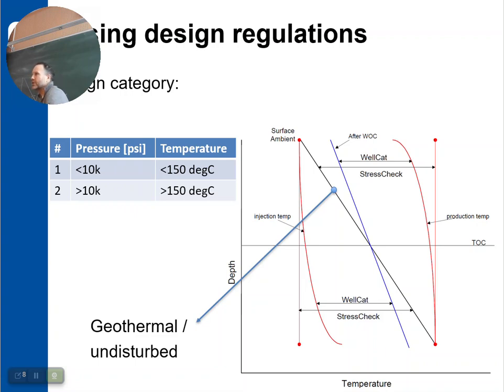Annular fluid expansion, AFE, not to be mixed up with authorization for expenditure, which is your budget for a well. Annular fluid expansion means the same mechanism as we are having here, gas migrating, and that's another dangerous mechanism that we have been talking about, right?